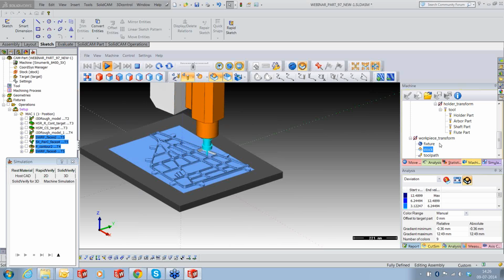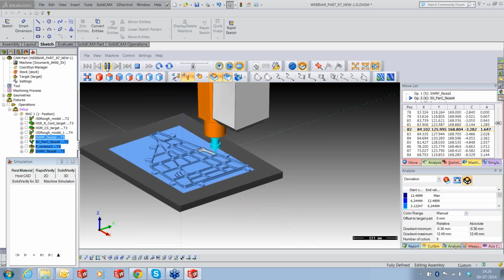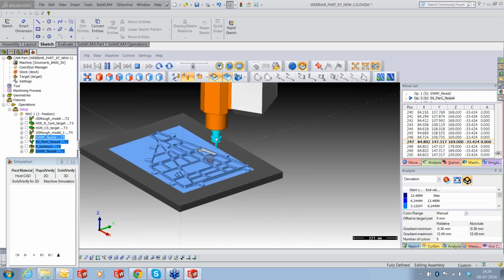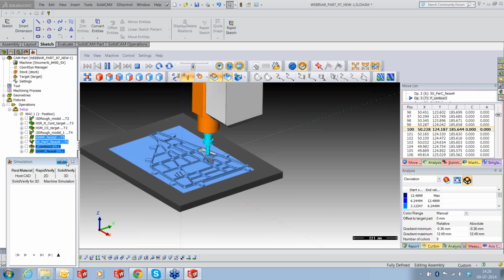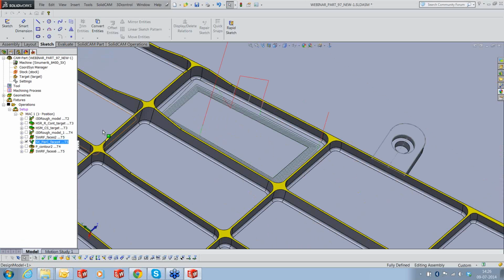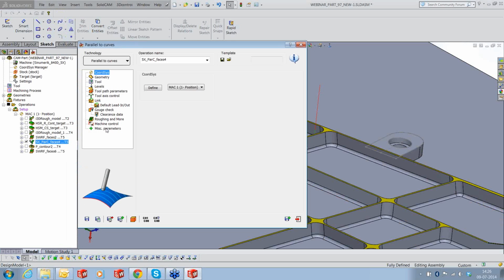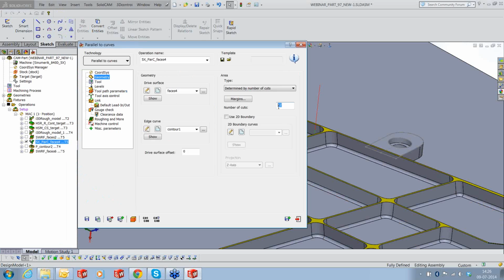Okay, let's stop this, go to the move and go to the next one. It's pretty quick. I can move between toolpaths. Very nice. You can see as it goes to the end, it's automatically doing the, oops, we had a problem. We need to check that toolpath. It's because of the number of passes. That was a problem. Let's edit and reduce the number of passes. Geometry, let's say 10 or even 8. Save and calculate.